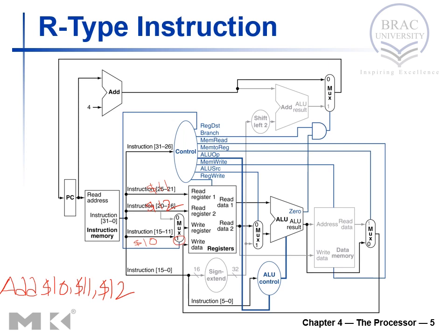And in the ALU, in this multiplexer, this port will be selected because this link will carry data coming from register 11, and this link will carry data coming from register 12.